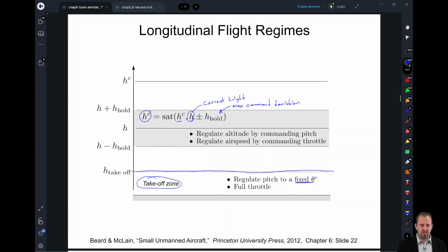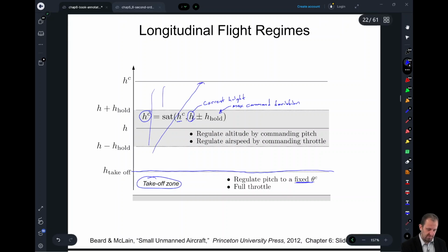That'll do a couple things for us. One, it'll avoid a bit of integrator windup, right? Because as we are trying to go all the way up to this desired height that's very high compared to where we started, that integrator is just going to be winding up the entire time. If we look at the area, we have a huge amount of windup.